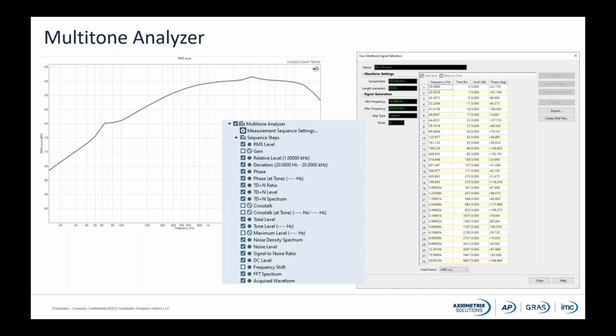The APX500 multi-tone measurement, as the name implies, uses multiple sine waves together. This signal is more like program material or music. Smart audio devices employ codecs which reduce audio data rates for streaming. Some of these codecs tend to mask sine wave signals, and as such, we must use a measurement requiring a stimulus signal other than sine waves.